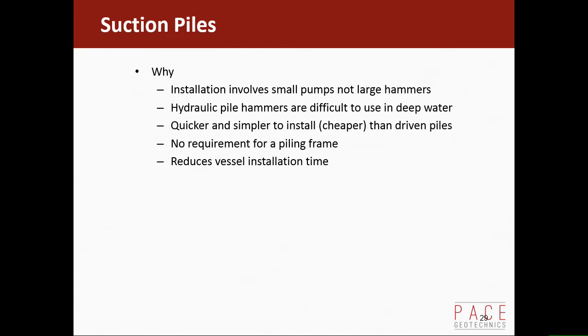Why would we use suction piles? Particularly on deep water jobs, a driven pile needs a lot of power to the hammer to drive it into the seabed. With a suction pile, a little pump will pump the water out and actually pull the pile into the seabed. So you can run it from a conventional ROV, and ROVs are ten a penny. Big hammers, especially deep water hammers, there's a handful in the world, if that. So that's a big reason for using suction piles.